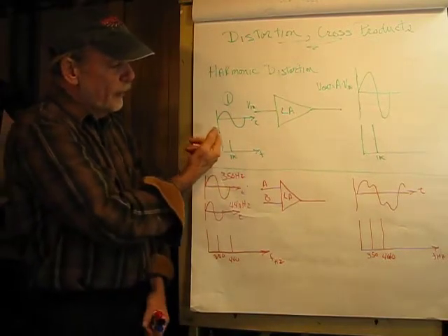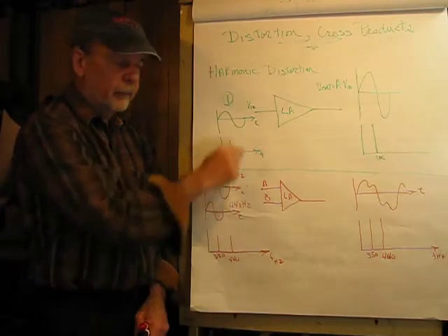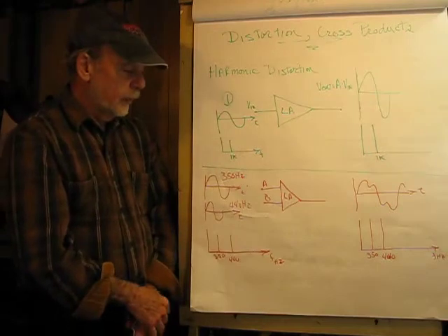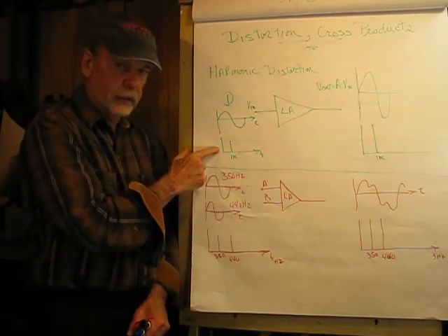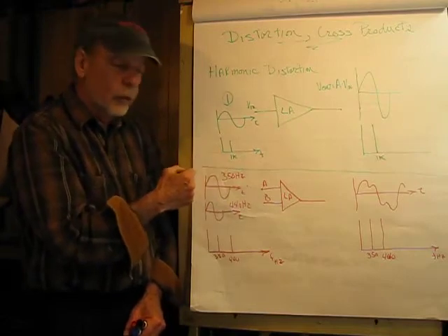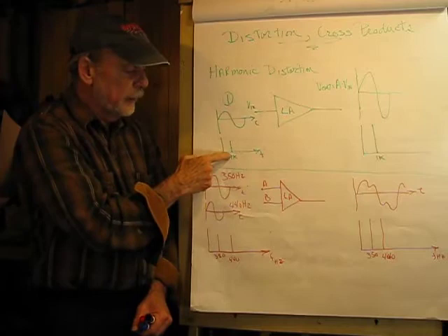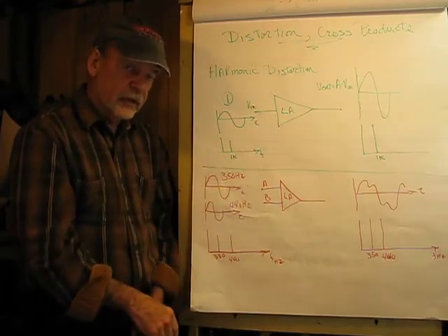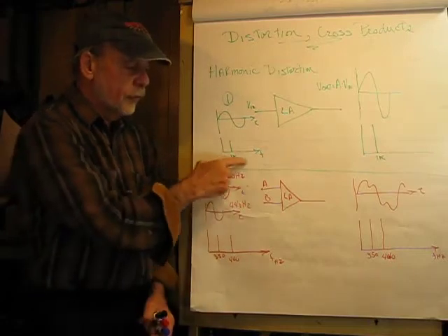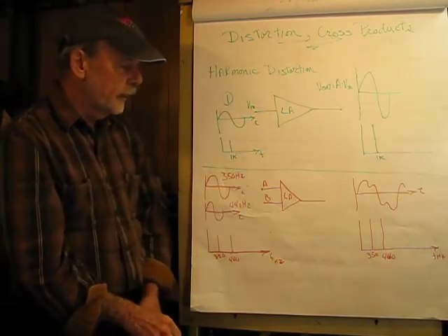So I'm going to be sending a sine wave in, that we can see here in the time domain, and if we were to look at that with a scope with a Fourier transform function, an FFT, or a spectrum analyzer, what we would see would be a spectral spike in the frequency domain. Now, Fourier was a mathematician that lived many years ago who figured this process out, and it's so very useful to us in electronics today.